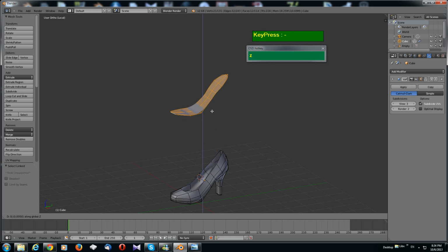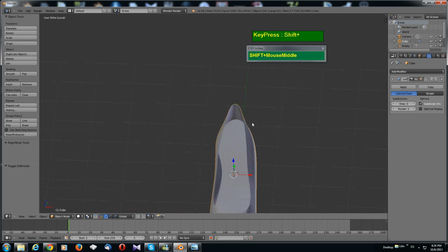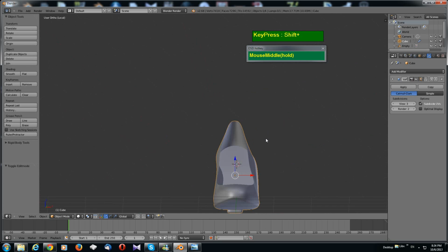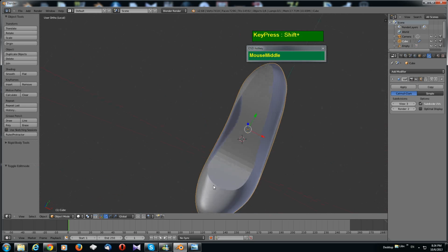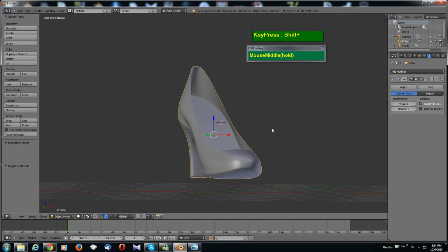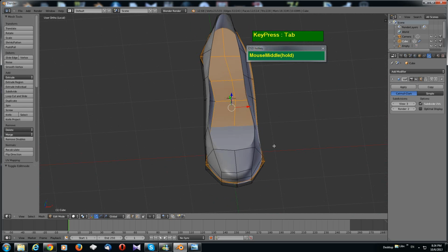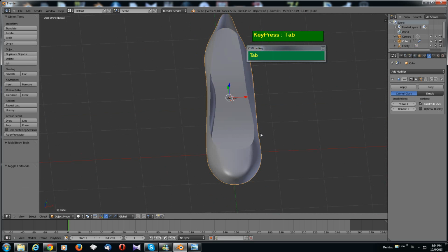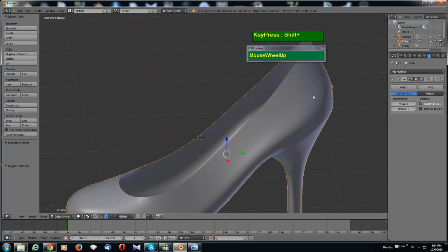I'm going to press -5. And then when you take a look at the shoe now, you have a sole inside. It is a separate element which you can actually assign a different color to. Now granted, the sole is actually slightly bigger, so you can scale it down slightly. I'm going to scale it down in the Z-axis slightly so that it doesn't protrude out of the shoe. You can see a little bit protruding here.